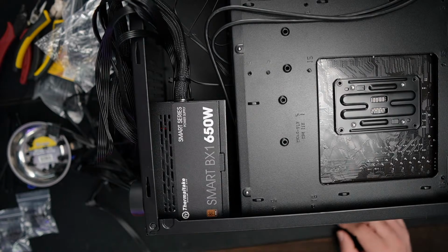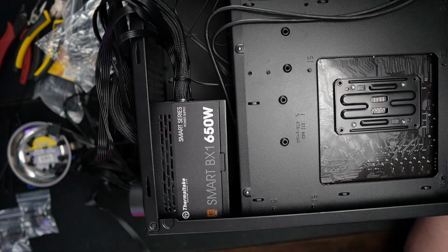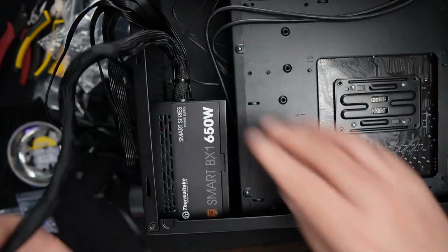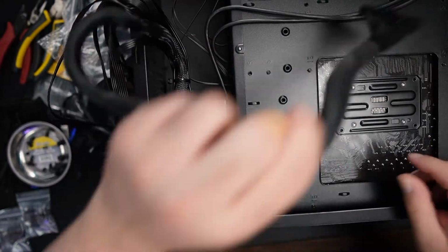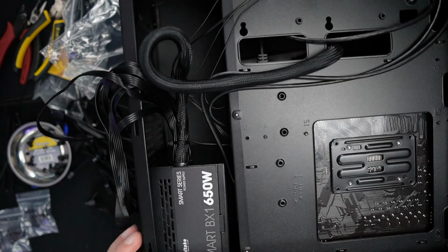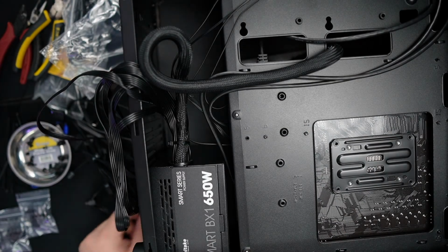Just going to clear off the desk a little bit so I don't have so much on here. Okay, we're going to take the cables down and we're going to take the 24 pin. Got to untangle it first because it's always tangled up in everything else. So just untangle that, and we're going to put it to the spot where it's going to go, which is the second hole up here, the first hole up there, whatever. It's a little bit further up than the other hole. And you're going to also put in the CPU one.